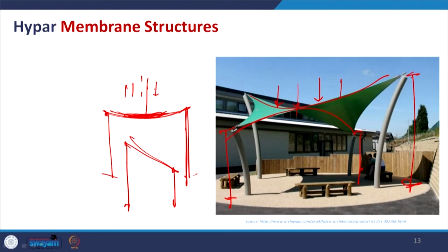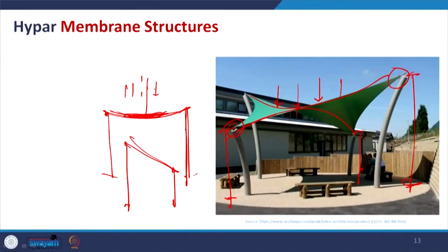So, this is a very good application of the tensile structure along with the membrane, and the structure is very simple. Like if you want to make it for an installation, you can simply use such a cloth which can be expanded a little due to this tension and all, and can get this kind of shade or Samiana we can refer to.